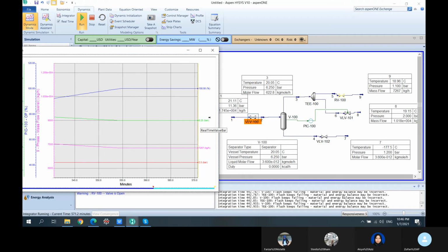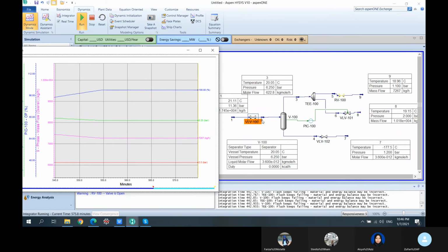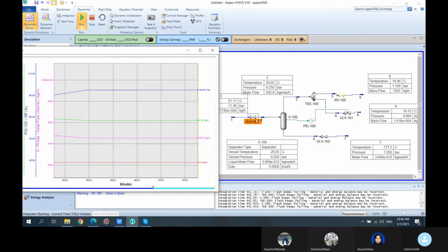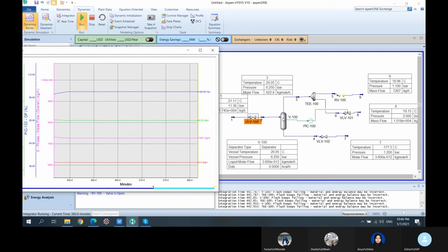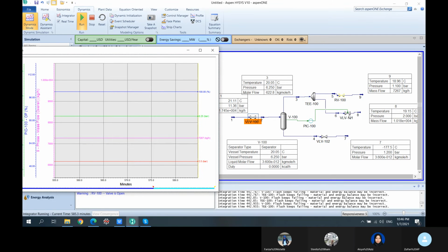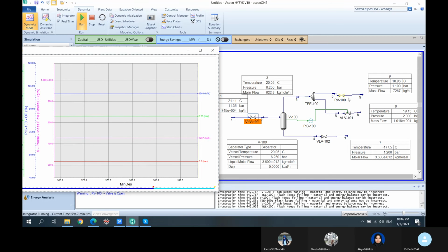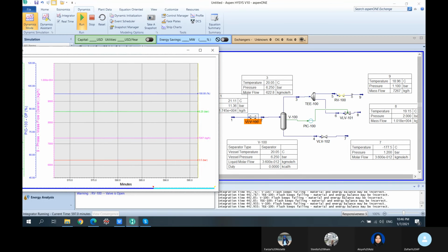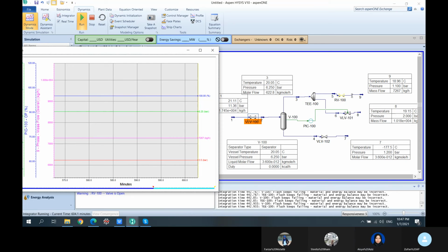Now, because we have this fully open at very high pressure here, we destroy the pressure somewhere here, and then it's just stuck at 6.25 bar. It's all steady, so we cannot reduce the pressure much more. The valve is already fully open. This guy is also open. There's nothing else. We need another relief valve then.